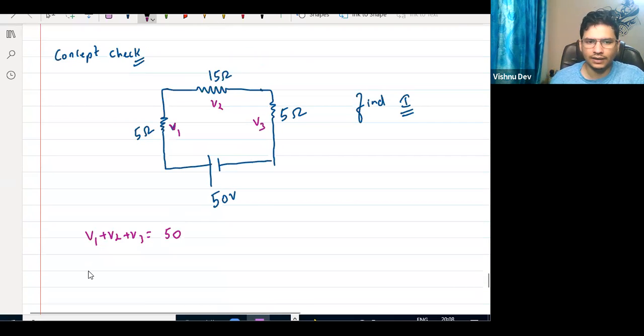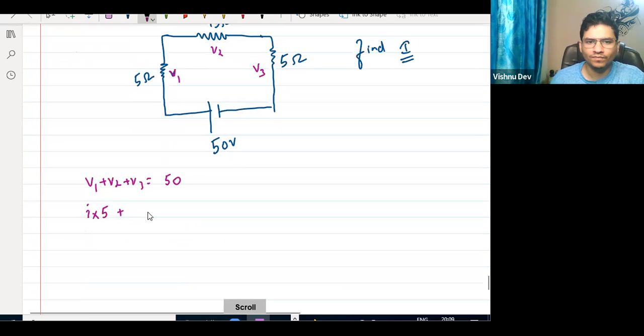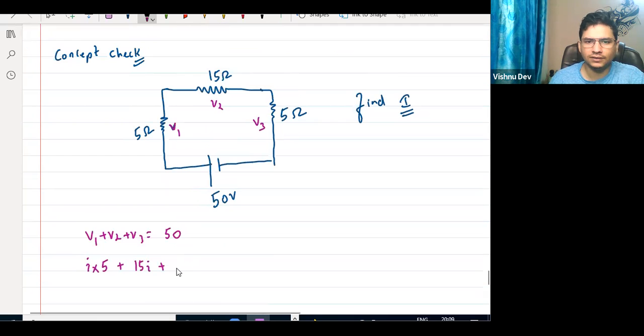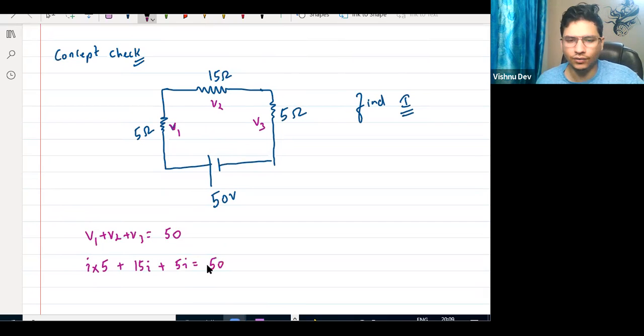And what is V1? V1 is I into R1, I into 5, 5I. Correct, 5I plus. What is V2? I into 15, 15I. Correct. Plus V3, 5I again. Equals to 50, sir. Okay. Got it, Tanushree? You understood your mistake?